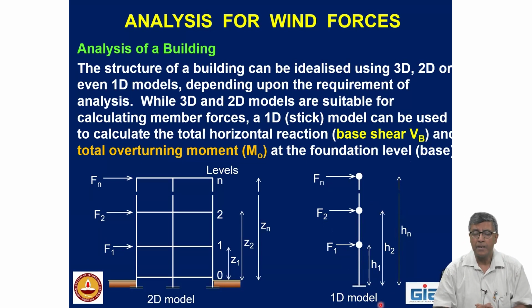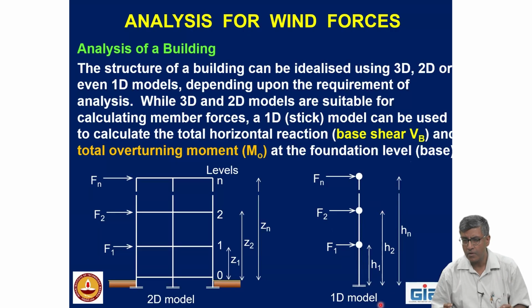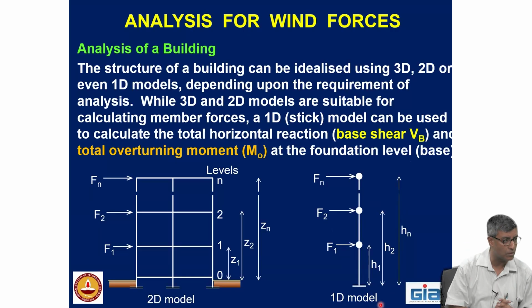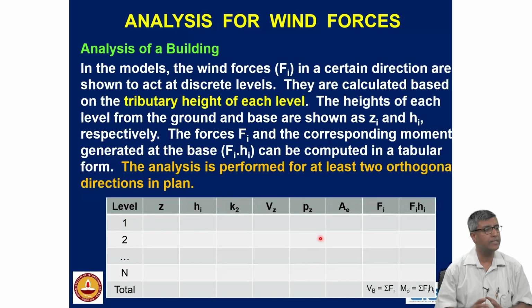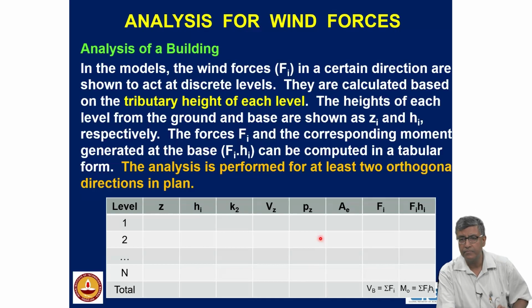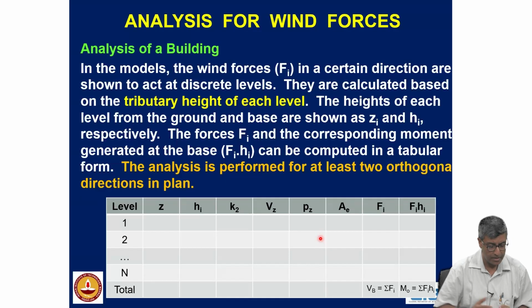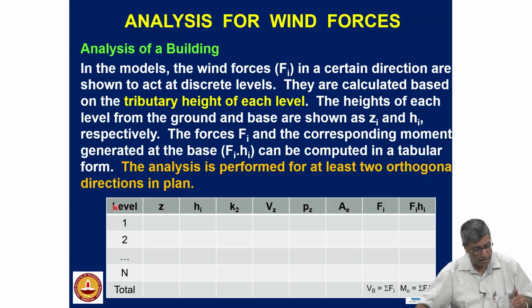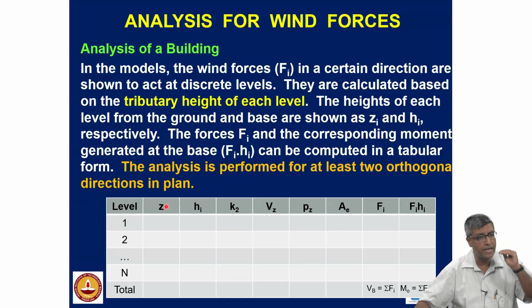You should learn how to do calculations fast. Once you have an estimate of this, then you can go for a computational model. Typically you will be doing the calculations in a chart like this. This is the way my teacher taught me, and this is the way I teach my students. On the rows at the different levels, you write the height of those levels.